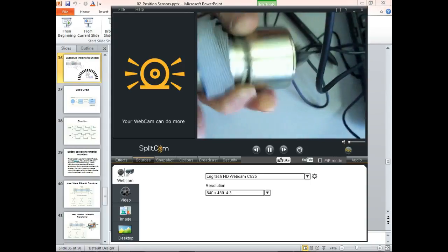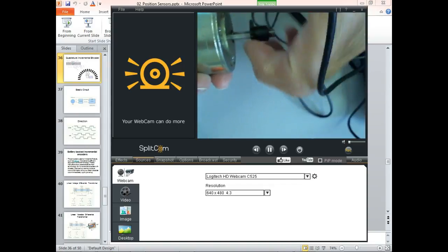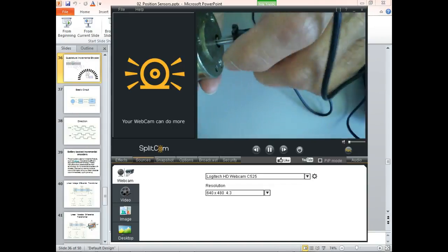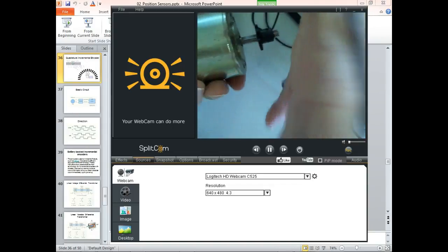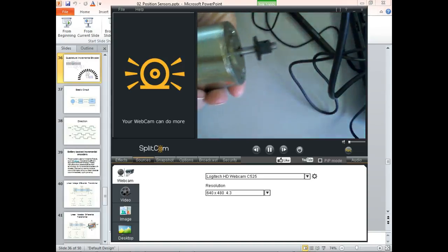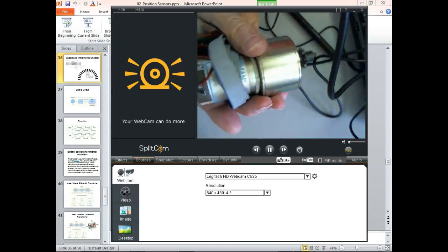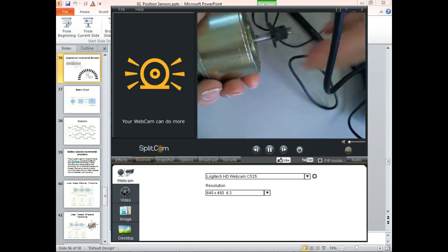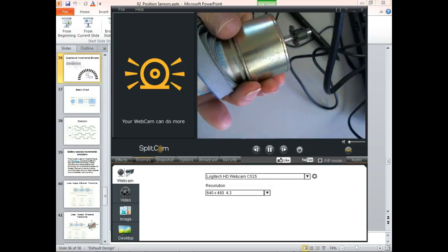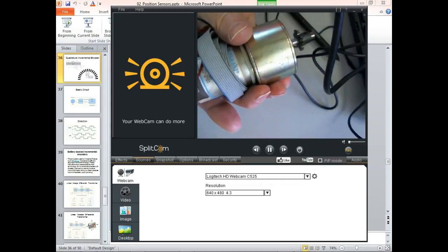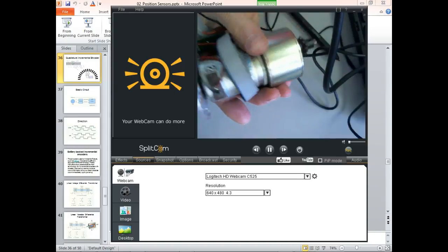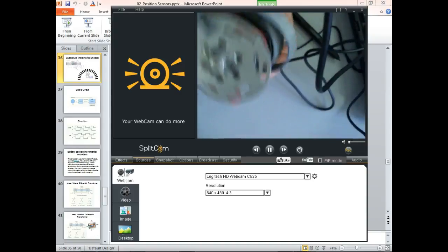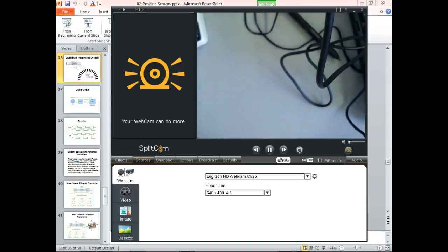So this guy over here is spinning like crazy. This guy over here is not moving near as much, right? And then we go through another gear reduction. We go from here to a bigger sprocket on the actual actuator itself. So to figure out what it meant from here to here, we would have to know the division ratio between this sprocket and the sprocket that was mounted to the joint on the robot. And we don't have the robot anymore. So I took all these off because it was really neat to see it. So I want to see it again.